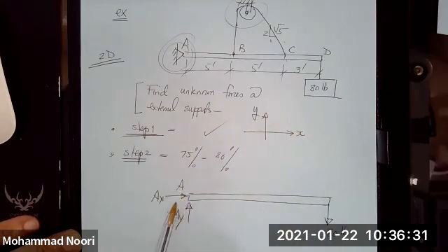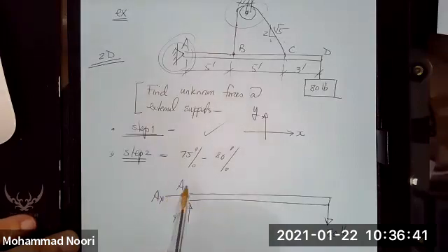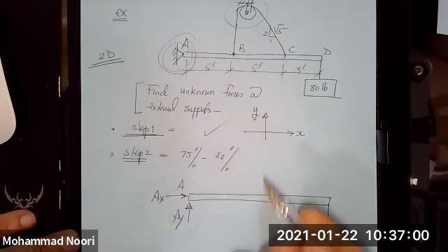We do not know how these forces are actually acting in order to keep the structure, but we always just make an assumption. We'll see that once we solve the problem, if the assumption is wrong, you end up with a negative value for these forces. But I don't care what direction you assume. Put anything you want, solve the problem, see if the assumed direction is wrong.